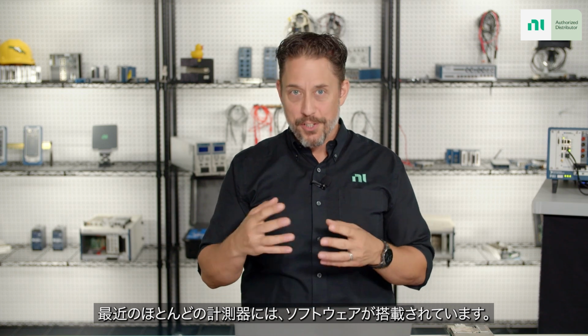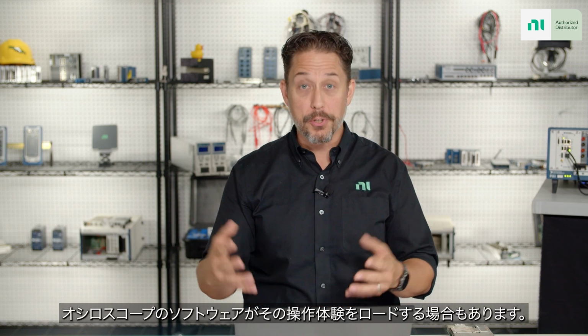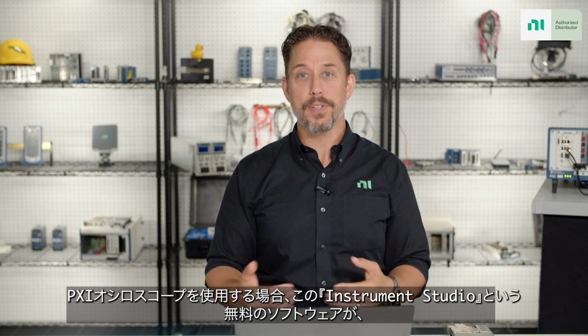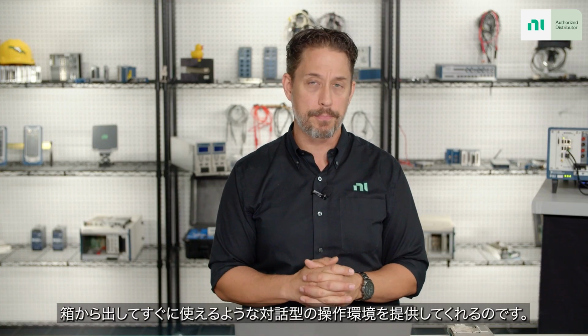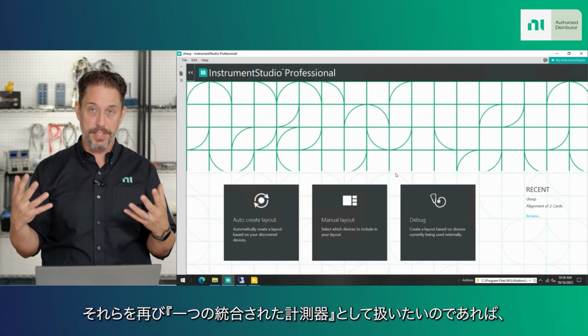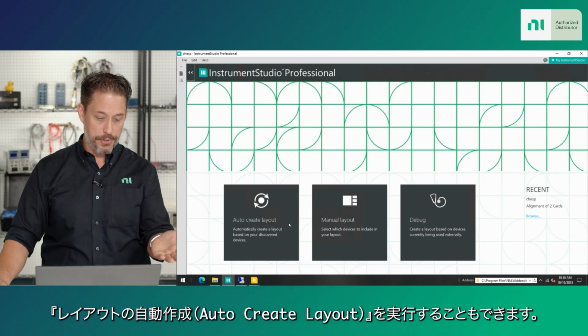So with most modern instruments, there's a piece of software. It could be an operating system like Windows, and then a piece of scope software loads. The interactive experience for using NI PXI scopes is Instrument Studio, a free piece of software that gives you that out-of-the-box experience. And so if you had multiple scopes in your system and you really wanted to, once again, look at them as one unified instrument, you would go through and you could do, say, an auto-create layout.